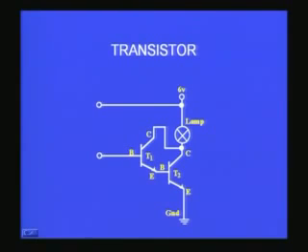But even if it is very high, of the order of megohms, you would find 6 volts by megohm will be very small currents, of the order of microamperes or less. Even that current, because you have a very large current gain, which is 10,000 or beta 1 product beta 2, will be able to provide enough current here and make the lamp glow. This is another demonstration which I would like to show to you. So let me just quickly show you these two demonstrations, and I will come back to the transistor characteristics, and then we will discuss that.